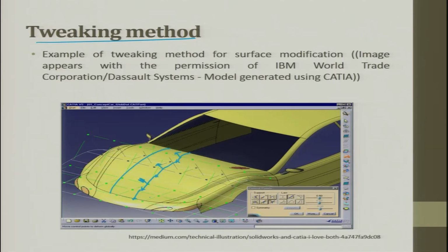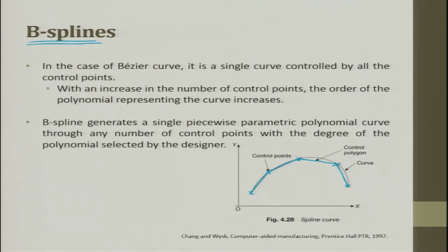Okay. So, it will look as though it is smooth, but when you watch very closely you can see several small facets or curve structures, because they have discretized the curve into several small control points. So, this is what is talked about in this B-spline. You have control points and you have control polygons.